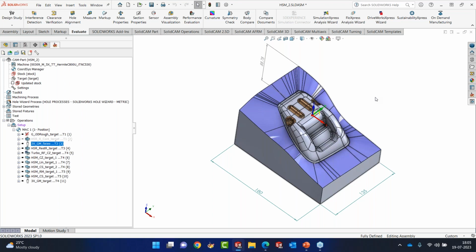It's neither too big like diameter 16, because the whole issue with bigger tools is that they draw a lot of power from the spindle. Most mold making machines are not very high powered, like 25 or 30 kilowatt; most are in the range of 7.5 to 15 kilowatt. So a bigger tool diameter ends up drawing a lot of power, and that slows things down. Although the turbo mode does allow it, it finds a limitation in the power of the spindle, tries to bring it down, and thereby drops the feed rates and other things.